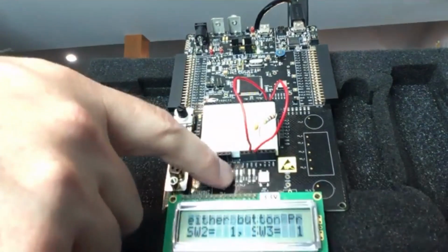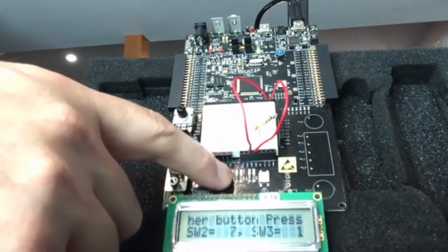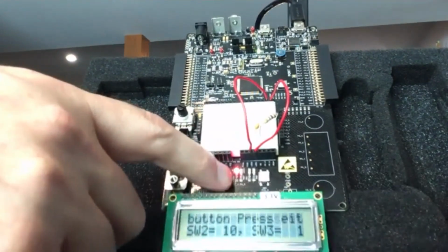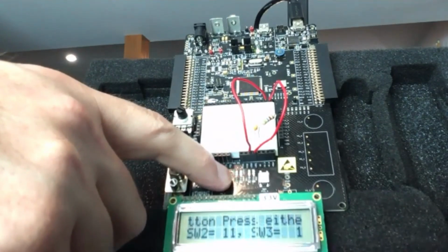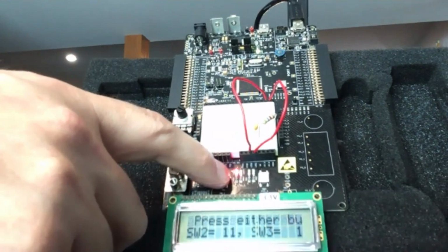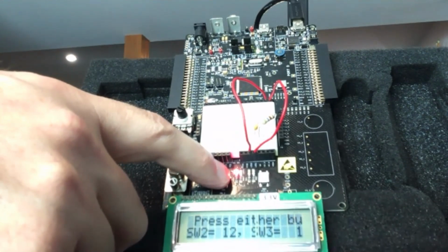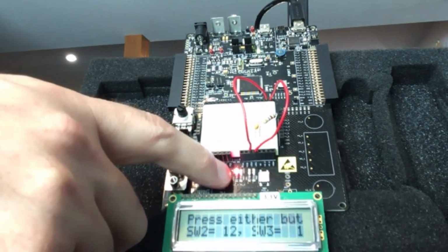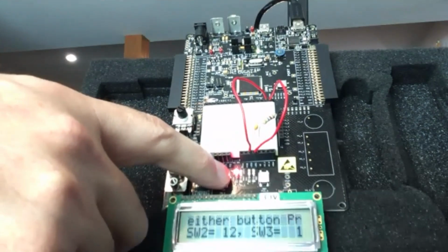And you'll notice that each time I push the button, it gives me exactly one count. It never gives me 2, it never gives me 0. If I hold it down, I get exactly 1. As soon as I push the button down, instantly the LED responds, the display responds, and actually I stopped scrolling the display. That's sort of a side effect of how I wrote my software. But it immediately updated things, and it never bounces.